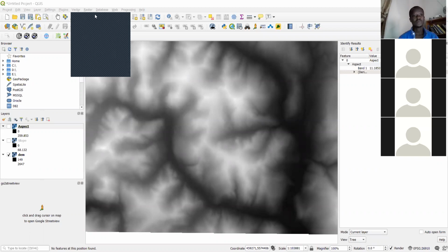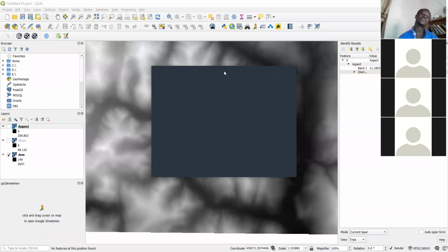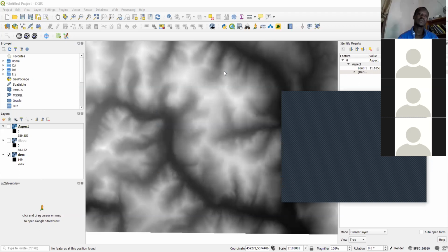Here we are with the topology tool. So topology should allow you to check if your layer is okay in terms of the lines, whether they are meeting at the right places or not. Because when you look at this data closely, you go in with the zoom in tool and then you zoom in. Okay, this is possibly Tetekwashi or one of those interchanges, but you see these kind of issues that you're having over here.